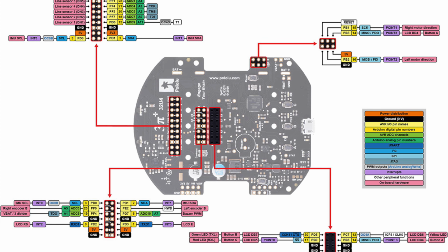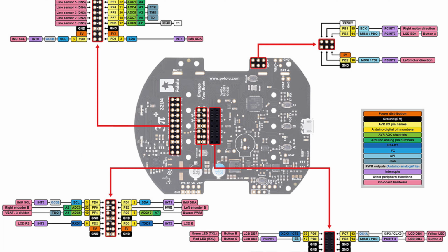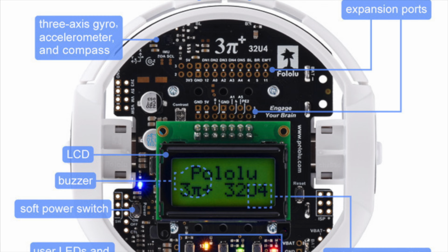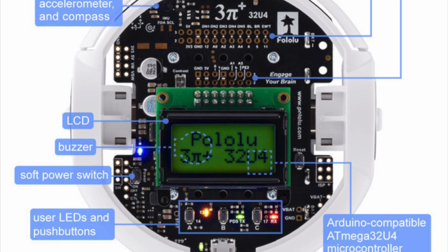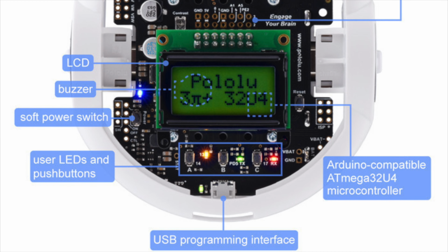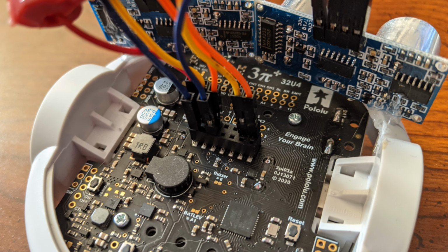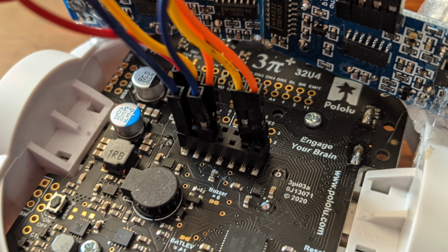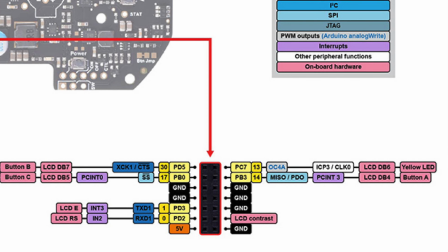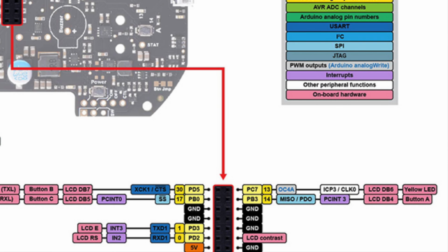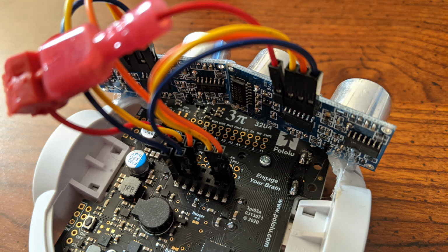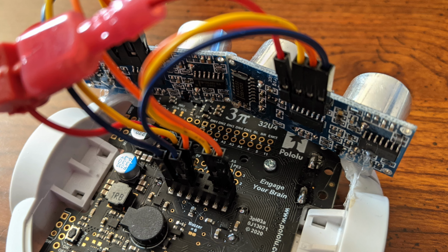However, you have to solder on the headers in order to do so. That is something I'm trying to avoid, or would like to avoid, because I want these videos to be focused on the programming of the robot and a little bit of the hardware, but I don't want to add any additional bars to entry. But luckily we can avoid all of that by removing the LCD and using the header underneath. There are 6 pins available there, as well as 5-volt connection and ground. The only gotcha is that there's only one 5-volt connection, so we're going to need to use it to power multiple devices.